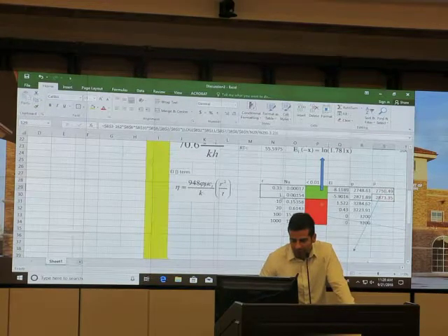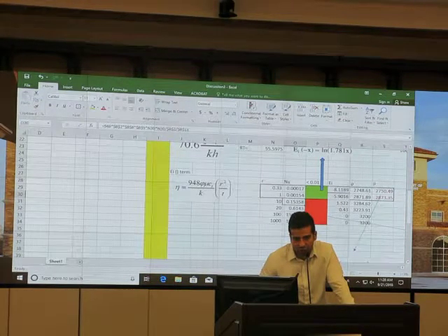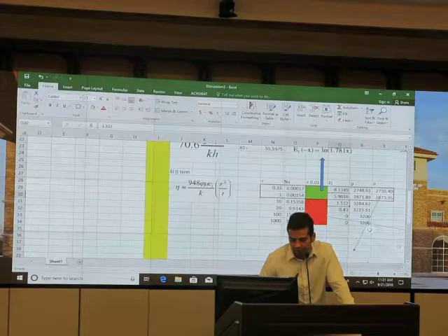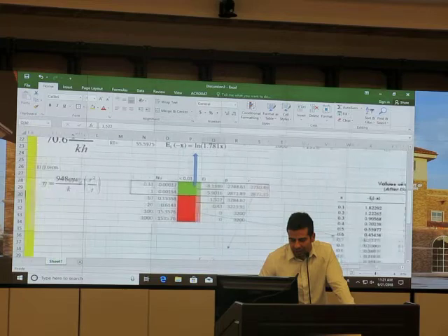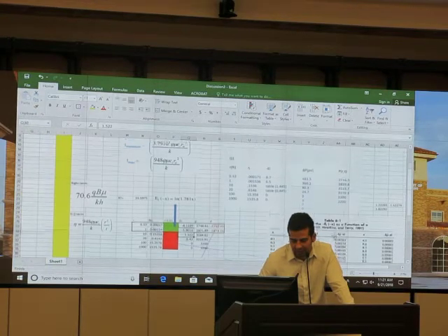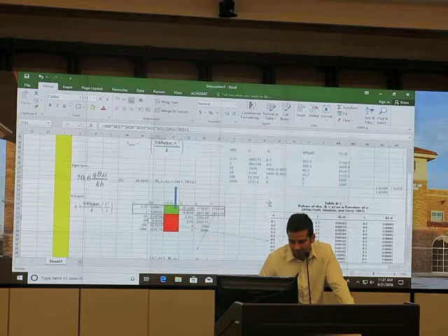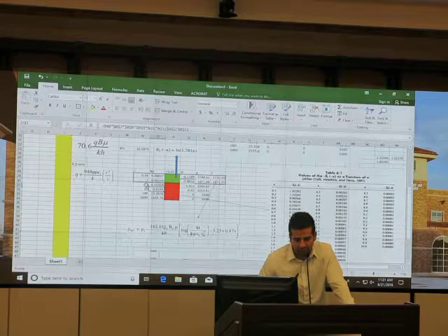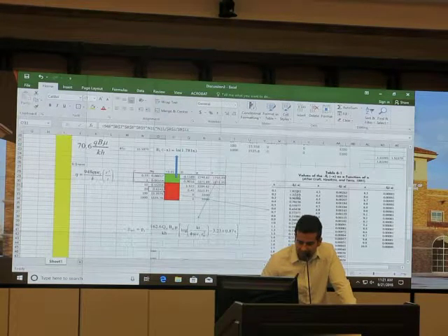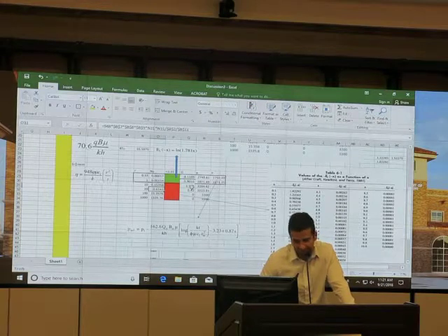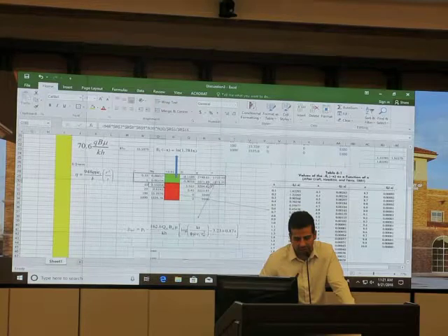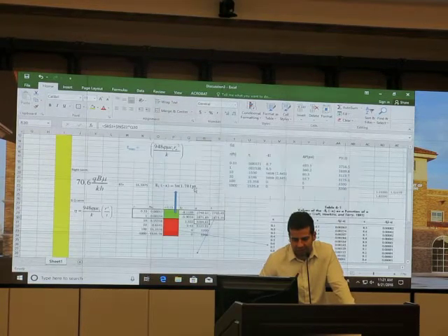Okay, let's move on. But what if the x, or nu, is more than 0.01? You use this table over here. It's simple, right? So you have the nu over here. Based on nu, which is x over here, you calculate the EI. So I calculated for r for nu 0.01, which is going to be in between. I get the average, which is an acceptable approximation. You get the EI function for that nu, then you put it in this equation, and you get the P.